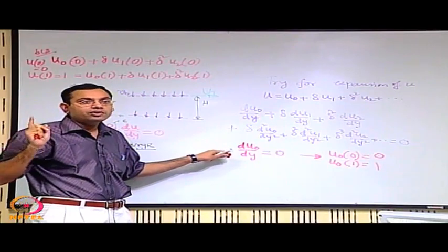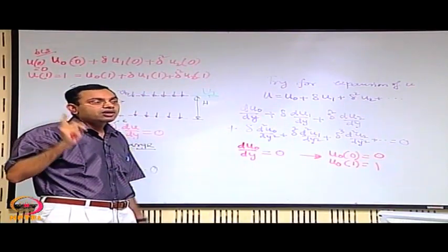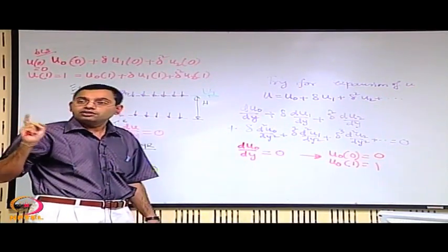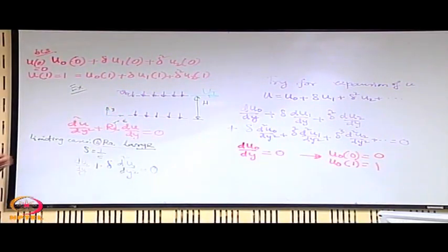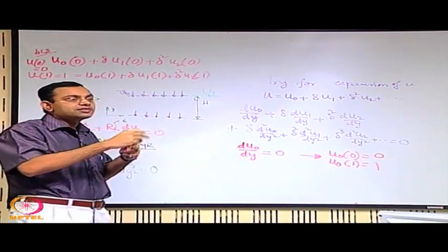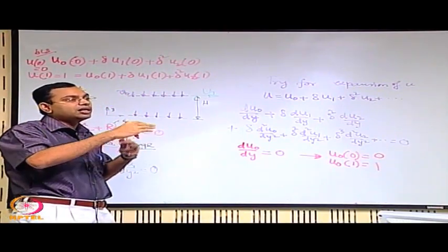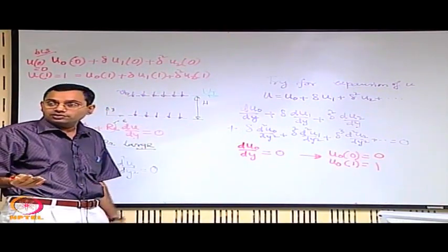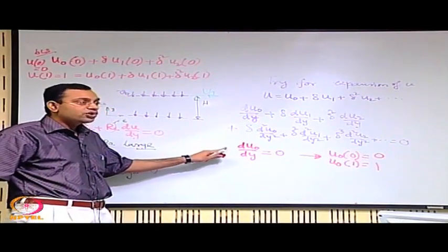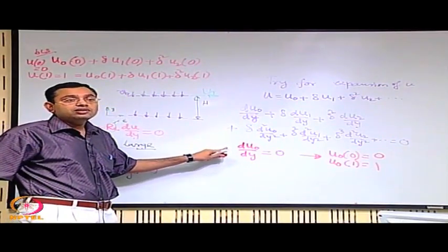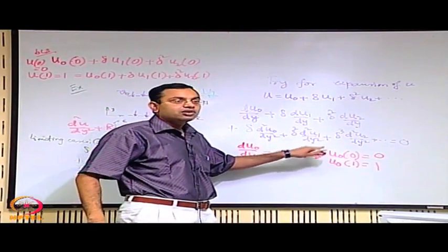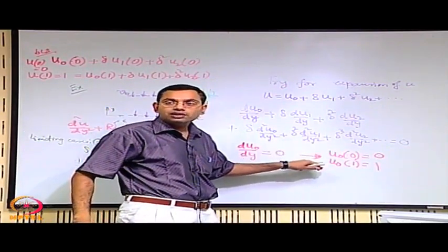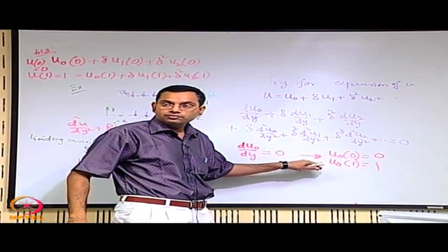So in whatever way you make an approximation, you cannot reduce the order of your governing equation, because then you cannot match with the boundary conditions which must be given by the proper higher order governing differential equation. So here the governing differential equation has forcefully got reduced to first order, although you have to satisfy the corresponding boundary conditions given by the requirements of the second order equation.